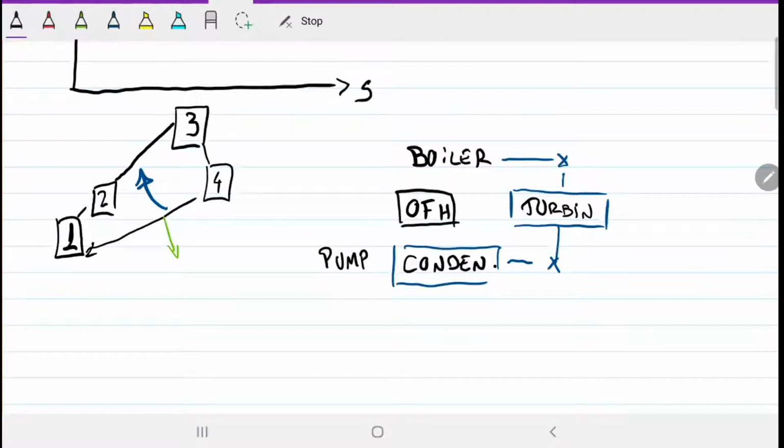Part of my steam is going to go like before to my condenser, but also part of it is going to go through our open feed water heater. Okay, so that means that we can actually save some of that energy, and we can mix all that up again.